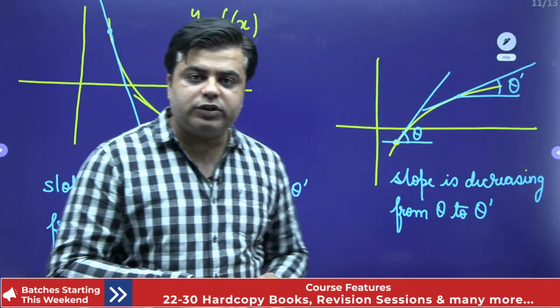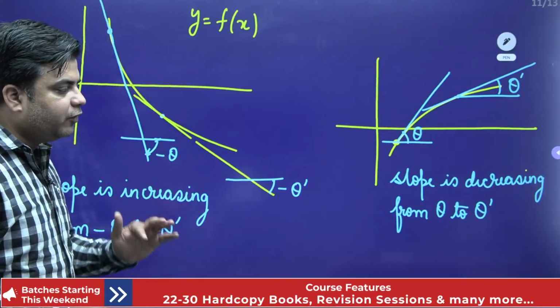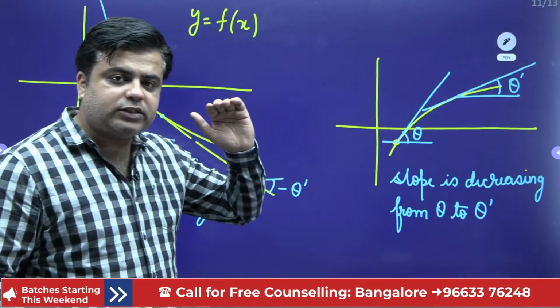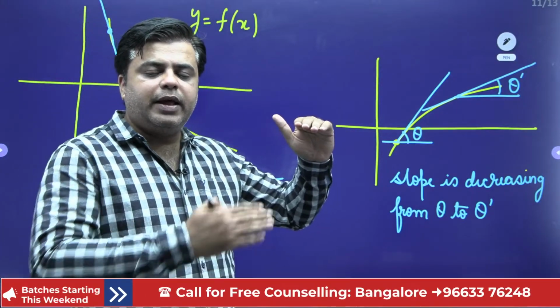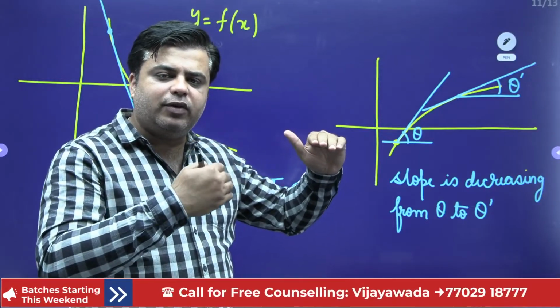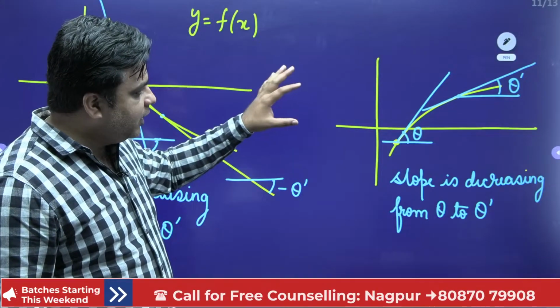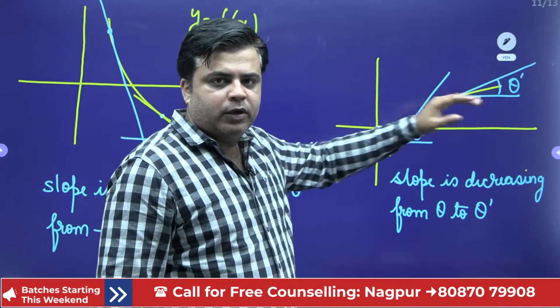The shear force diagram is the derivative of the bending moment diagram, okay? So we need to check the slope of the bending moment diagram, and the slope of the bending moment diagram is going to tell us about the shear force diagram. So in that analysis, we require this part.